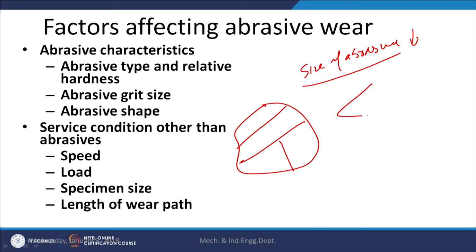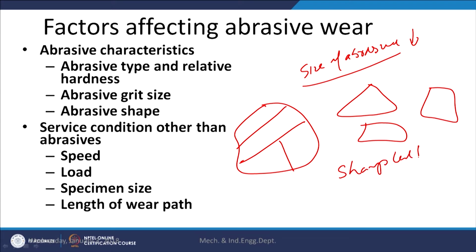These sharp-edged pieces produced by the fracture of large abrasive particles have sharp cutting edges, and these sharp cutting edges promote the removal of material by abrasion as well as metal cutting.